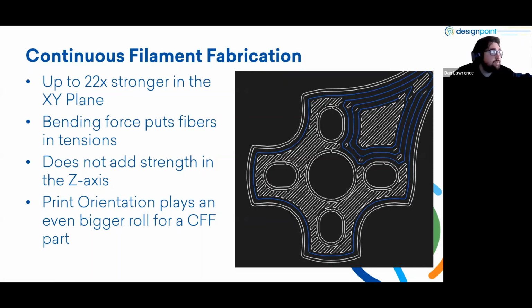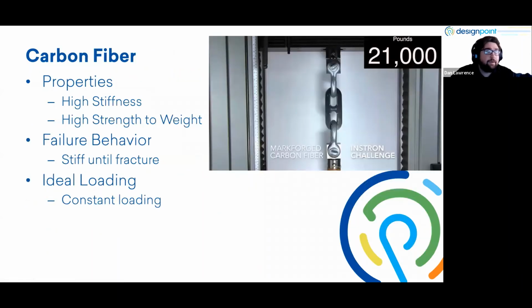But the fiber that we chose to use was carbon fiber. It was a close call between either carbon fiber or Kevlar. We ended up going with carbon fiber because of its weight. It's a lot lighter than Kevlar. Kevlar is a bit stronger, but we wanted it to be as light as possible because we want our quadcopter to be as fast as possible.